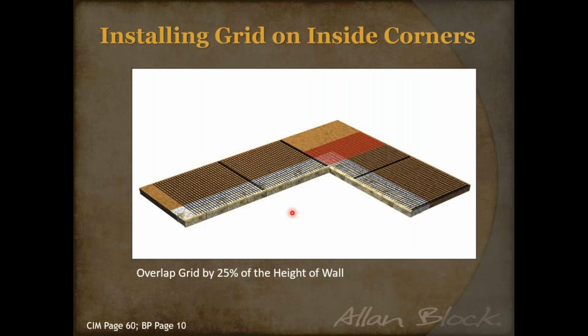Okay, so let's talk about it. I did the grid for curves. I've got to do the grid for corners. All we're going to do is change where that grid is going to be located. The best thing is, don't stop putting the grid right where the faces stop. You need to extend the grid into that hillside, so that we've got this inside corner reinforced as well.